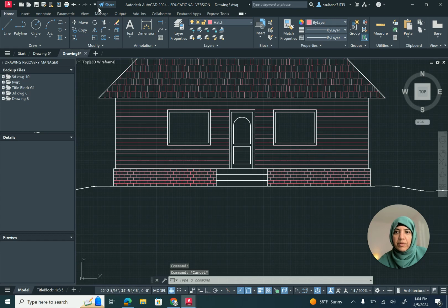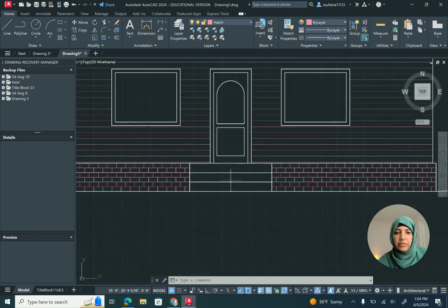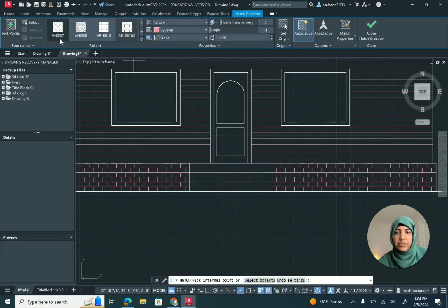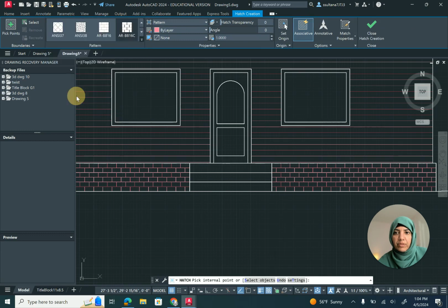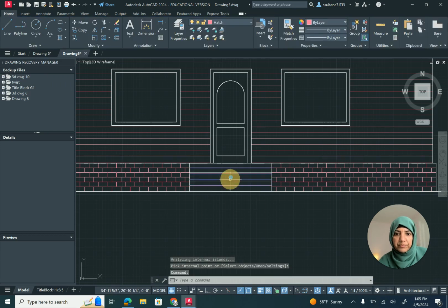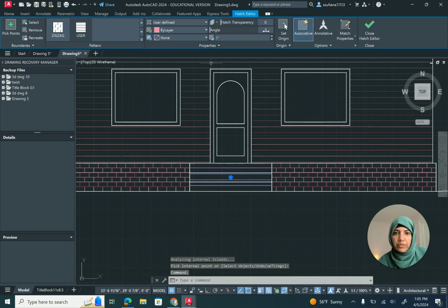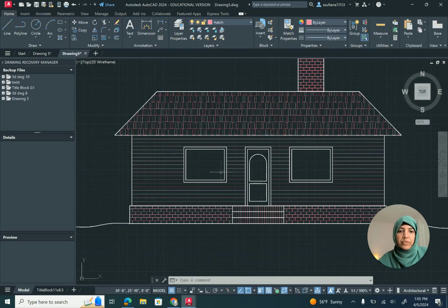Okay. And vertical lines over here, the bricks are vertically stacked here. So now you can use the hatch at the end, that is user hatch, and change over here the orientation. Make that 90 degrees so it becomes vertical. Spacing, let's change it to 3. Yeah. Now to give some color to the door and the window, we can use the solid hatch.